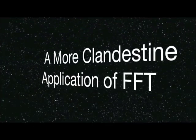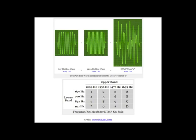Suppose you record someone dialing a number on a touch-tone phone. The DTMF, or dual tone multi-frequency signal, is a set of two frequencies combined to create a single tone. Using FFT, you can separate the two frequencies and determine what number is being dialed. Here is a phone number being dialed on a touch-tone phone. The question is, is it Professor Knospe's personal cell phone number or the number to the local field office for the FBI?